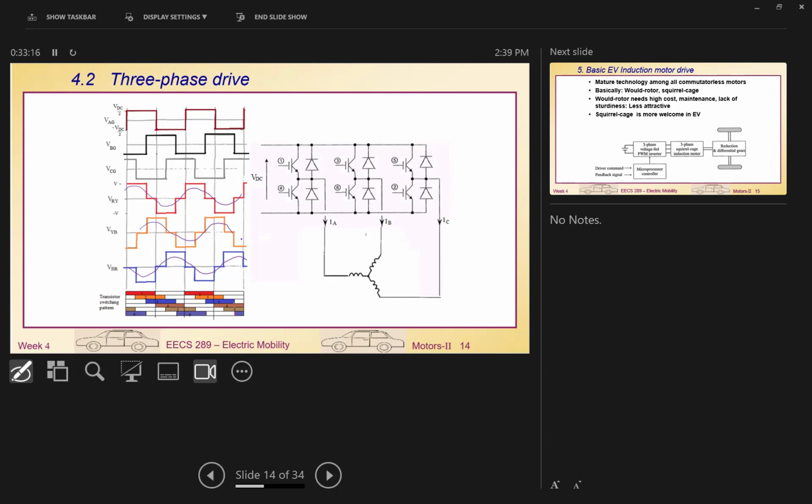That's why when you measure the current of the motor, it's still a sine wave, because there is a huge inductor inside. So that's the vision for all integral drives: it's not necessary to put in a filter. The filter is already inside the motor. Okay, save the money.